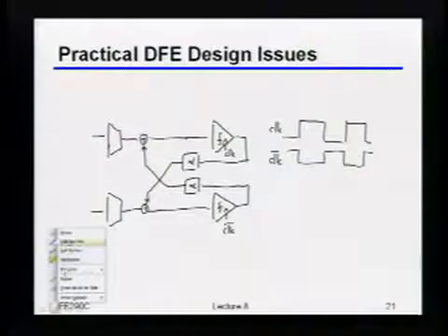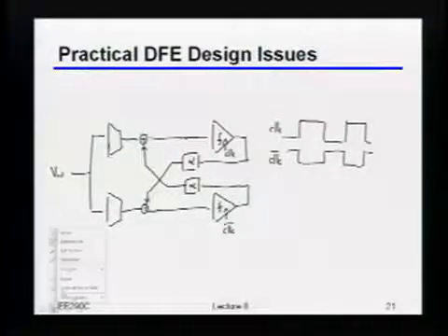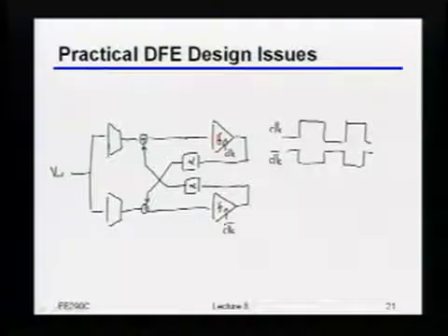And just to make sure there's no confusion, these are, of course, tied to the same input voltage. Okay? The reason I was mentioning this was, I may have gone to this interleaving because, as an example, I wanted to relax some of the constraints on my comparator. But notice, because I'm actually closing this first tap here, I still have the timing constraint of making the decision, going through this scaling, feeding back onto this analog node, and having it settle all before that next bit time. Because in this case, if I have DDR like this, each clock phase is a bit.